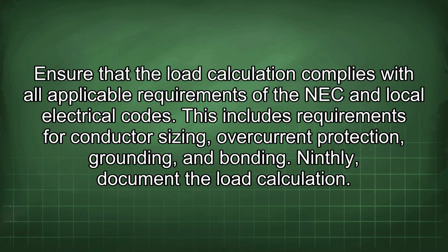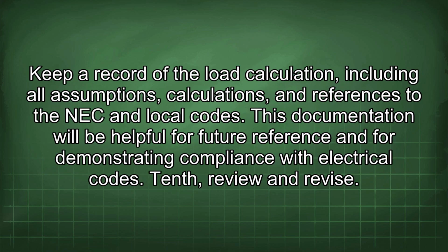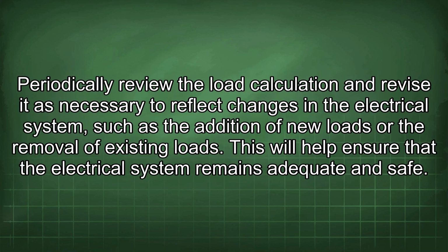Ninthly, document the load calculation. Keep a record of the load calculation, including all assumptions, calculations, and references to the NEC and local codes. This documentation will be helpful for future reference and for demonstrating compliance with electrical codes. 10th, review and revise. Periodically review the load calculation and revise it as necessary to reflect changes in the electrical system, such as the addition of new loads or the removal of existing loads. This will help ensure that the electrical system remains adequate and safe.